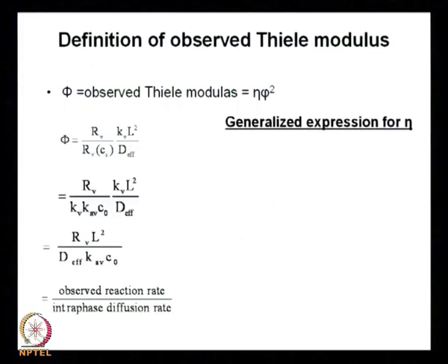Shape normalization, right. For different shapes you can come up with the same expression, and as I said before, the expression that we are going to use is not going to be completely accurate for all shapes, but it is going to be very close to accurate. There is going to be maybe 5-10% error, but even with 5-10% error you are pretty close, because in shape normalization you cannot have 100% accuracy. Okay. So, the expression that we are going to use is this, eta equals tanh phi over phi.